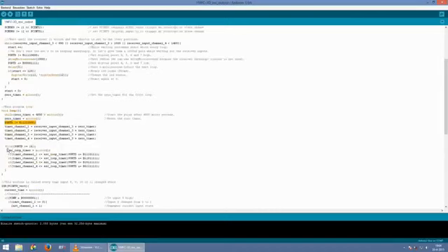This while loop is executed until the 4 highest bits in the port D data register are 0. This equals the finishing of all the ESC pulses. Inside the loop, the delay times are checked. When the delay time expires, the corresponding port is set low. When all the ports are low, the while loop is terminated.